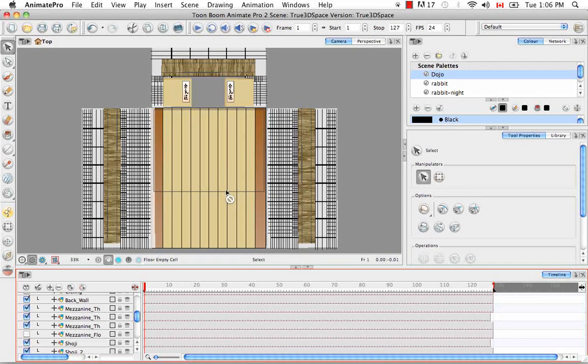The one thing to remember when you're creating a piece of architecture is that generally there's a lot of repetition. And when there's a lot of repetition, you should be using the duplicate, flipping, copy, pasting, rotating tools a lot, because you're never going to individually draw just this one piece of the mezzanine balcony and then draw this one separately. You're obviously going to copy this and paste it over here to have a different version, and then maybe paste it over here and cut off part of it, or vice versa. Create this one first and then add a few paneled sections to it.